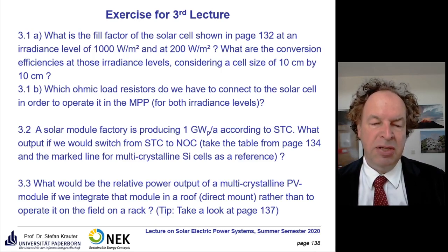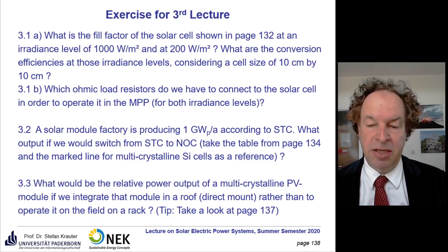The last part is, what would be the relative power output of a multi-crystalline PV module if we integrate that module into a roof and the temperature increases? We take a look at this table on page number 137 and then determine the power loss and the yield loss.